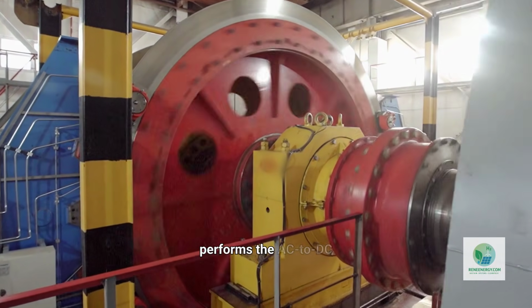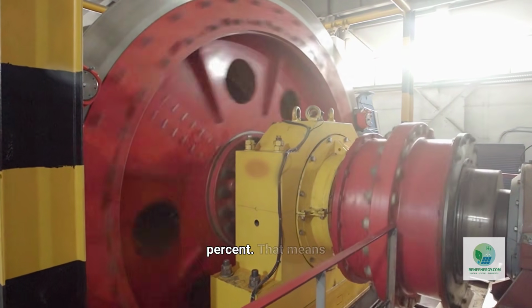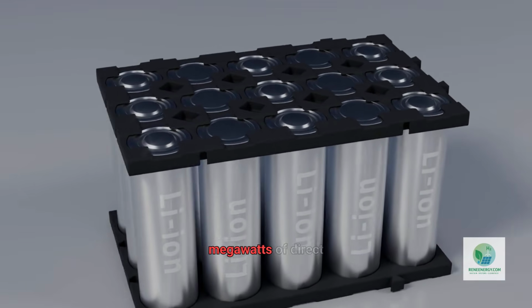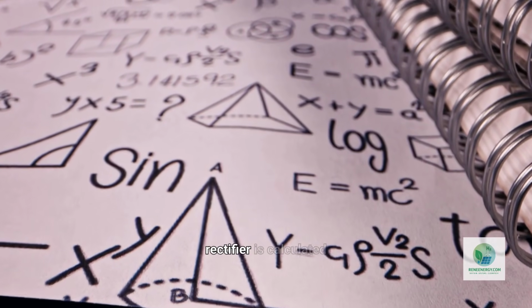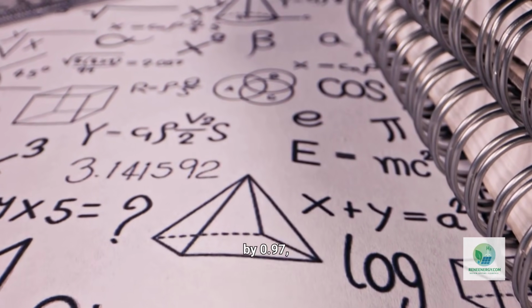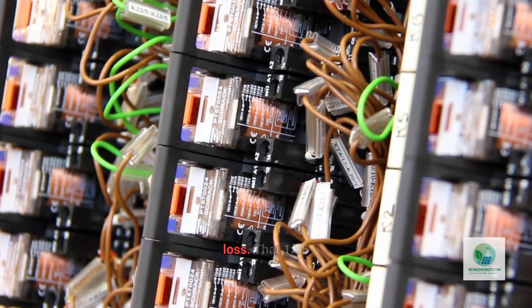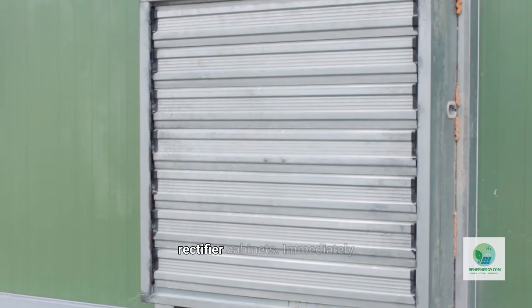The rectifier performs the AC to DC conversion at an efficiency of 97%. That means 3% of incoming electrical energy is lost during conversion. If the electrolyzer stack requires 50 megawatts of direct current power, then the required AC input to the rectifier is calculated as 50 divided by 0.97, which equals 51.55 megawatts. The difference, 1.55 megawatts, is conversion loss. That 1.55 megawatts appears as heat within the rectifier cabinets.